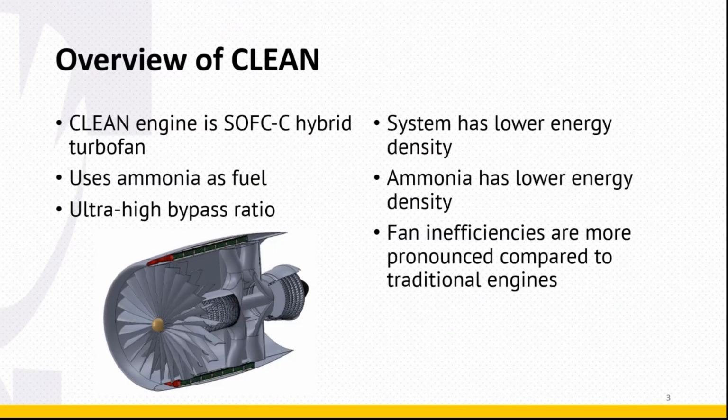So, brief background of the CLEAN project. CLEAN stands for carbonless emissions in aviation. A CLEAN engine is a solid oxide fuel cell hybrid system. It's a fully mixed turbofan, and the goal is to have zero emissions other than water and nitrogen. So we're using ammonia as the fuel for both the turbine and the SOFCs.